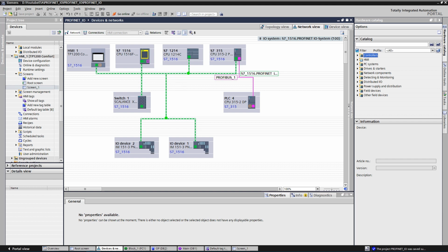But unlike the PROFIBUS, PROFINET operates on higher carrier frequencies, which are from 100 to 600 MHz, while carrier frequencies of the PROFIBUS are 3 to 20 MHz. There can be used 2 to 4 twisted pair cables. It enables a bandwidth from 10 to 1000 megabaud per second, while maximum bandwidth of the PROFIBUS is 12 megabaud per second. Different cables can be used in the same application, depending on your used hardware.